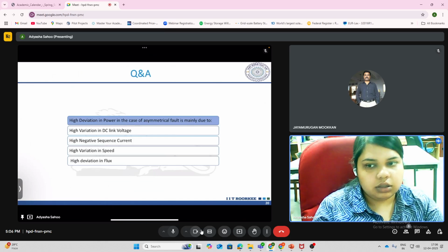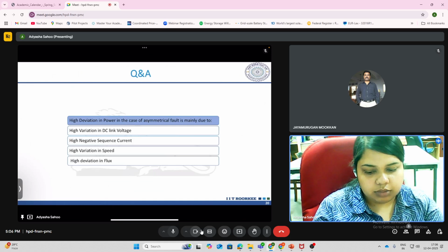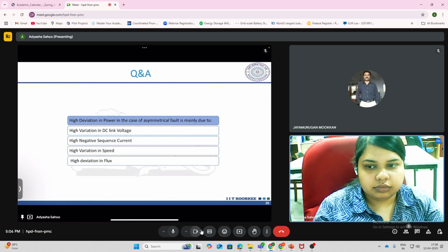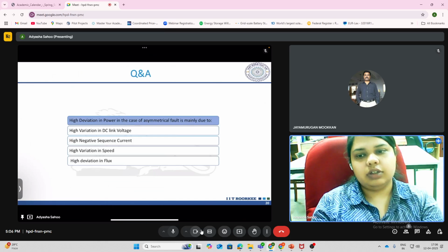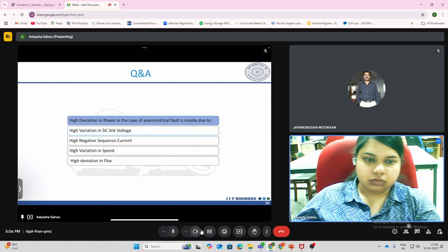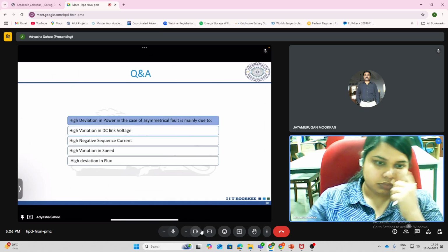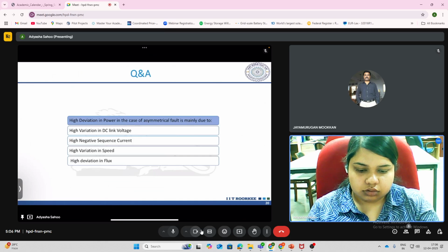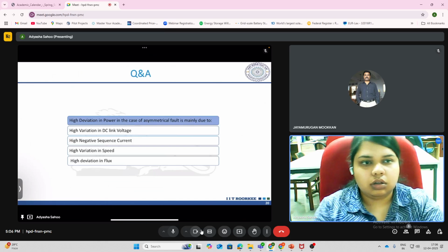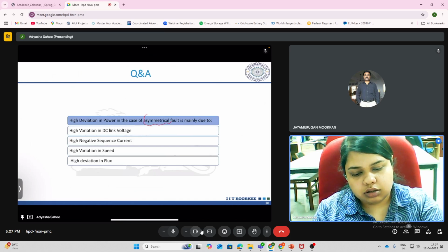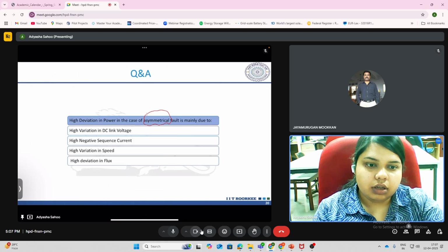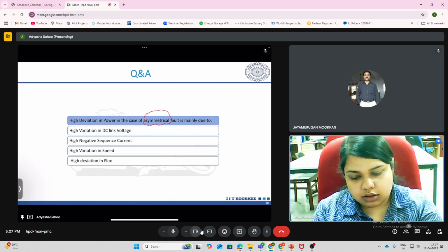Now coming to the Q&A session. The first question is: the high deviation in power in case of asymmetrical fault is mainly due to what? High variation in DC link voltage, high negative sequence current, high variation in speed, or high deviation in flux. We had seen that due to the asymmetrical fault, you will have the presence of negative sequence components. So the correct answer is high negative sequence current.